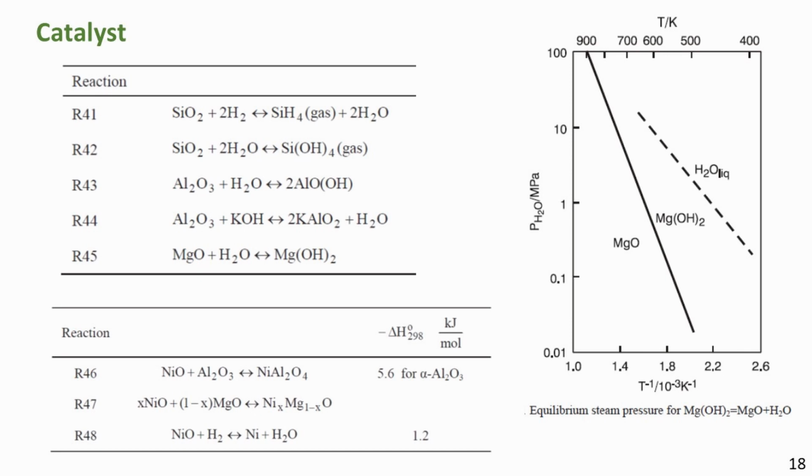High surface area supports such as gamma alumina can be used for catalysts for low temperature adiabatic reforming, but these supports suffer from substantial sintering and weakening at temperatures above 500 degrees. Because silica is volatile at high temperature in high pressure steam, it is now excluded from catalysts for steam reforming. Alkali used as a promoter to eliminate carbon formation may escape slowly from the catalyst.